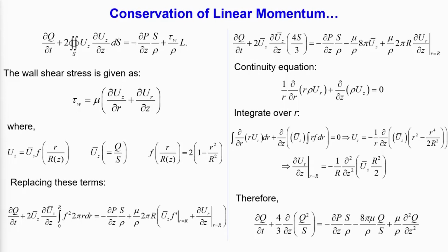and so with this velocity profile you can do the integration analytically and you will get that equation which is there at the top, and in that you have a velocity gradient at the wall, and to get the velocity gradient at the wall you integrate the continuity equation in the differential form, and from there you will get the value of velocity gradient at the wall in terms of the average velocity. And why average velocity is important? Average velocity is simply the flow rate by the cross sectional area.